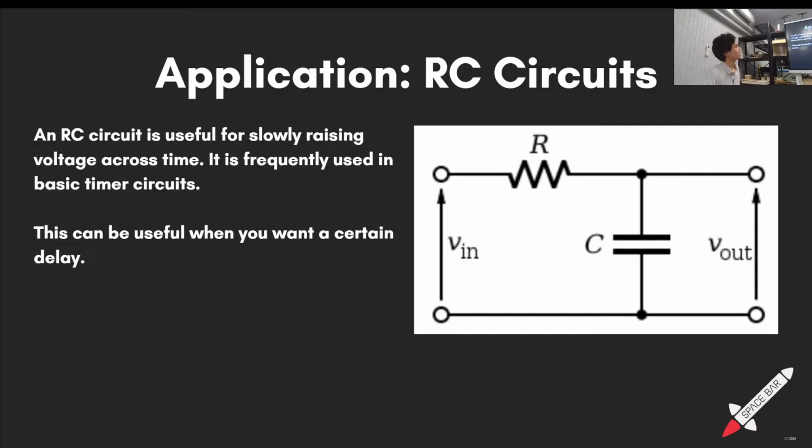Okay? And then you can choose specific R and C values in order to get the desired delay time given the input voltage and a few other parameters. Use an online calculator, don't think about the math. Okay? Everyone happy? It's like a mini drawing.